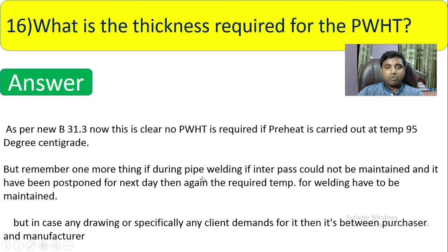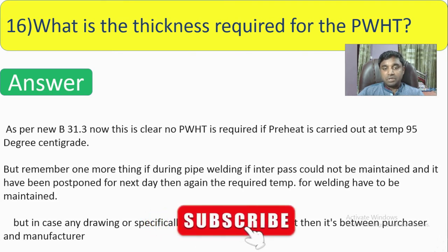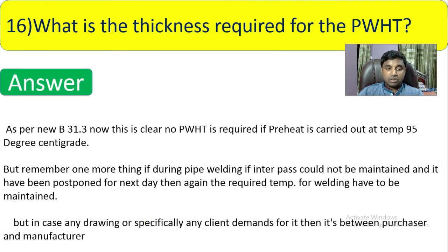But remember one more thing, if during pipe welding the interpass could not be maintained and it was postponed to the next day, then again you require temperature. Definitely your client may ask you to do the PWHT, because the interpass today was not maintained, and you are doing the interpass again tomorrow. So that joint may be affected. In that case, the drawing or any client demands that you have to do PWHT. There should be a written document in your procedure.